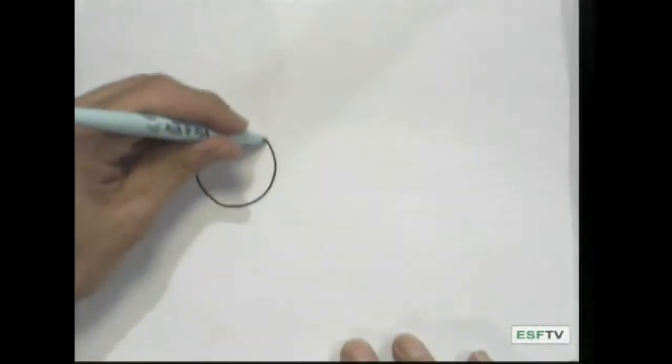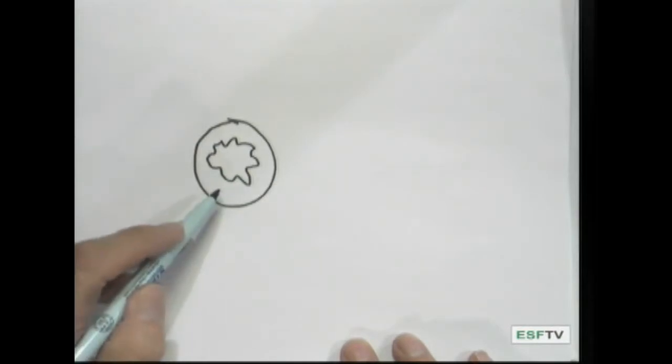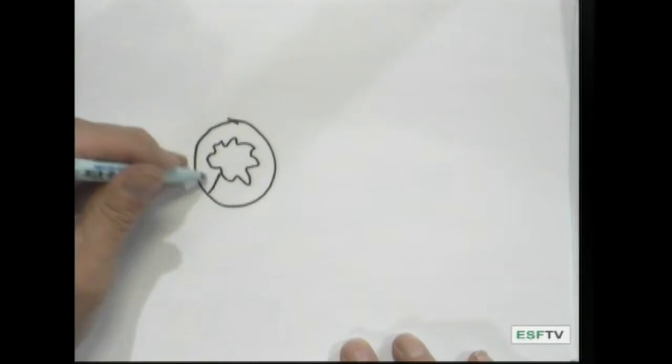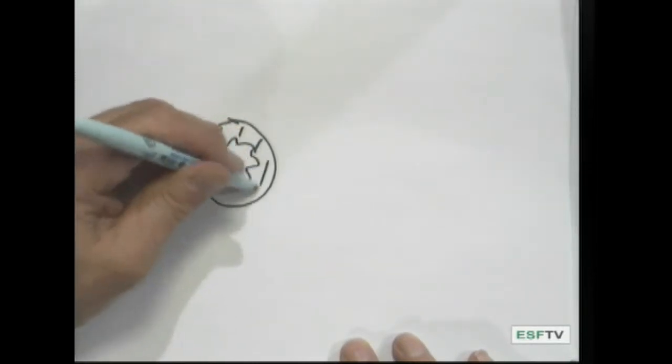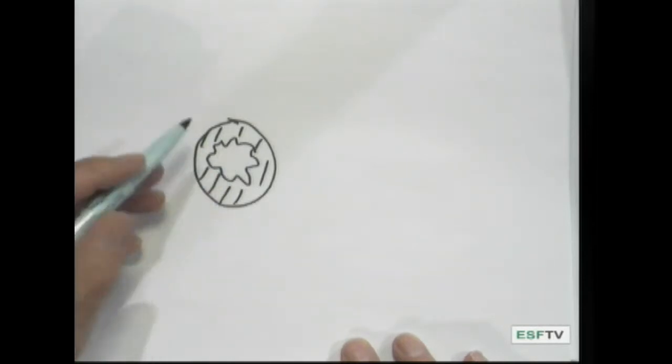If you look at the different kinds of shapes of bones, the long bones, of course, as we illustrated before, are more or less like hollow tubes. If you cut them across in cross-section, they will look something like this, with bony matrix out here that is bearing most of the load, and then an empty space in between, which is where you have marrow and things like that. Now, the second moment of area can be calculated fairly easily for something with a circular cross-section, but this doesn't mean that other kinds of shapes can't have second moments of area as well.